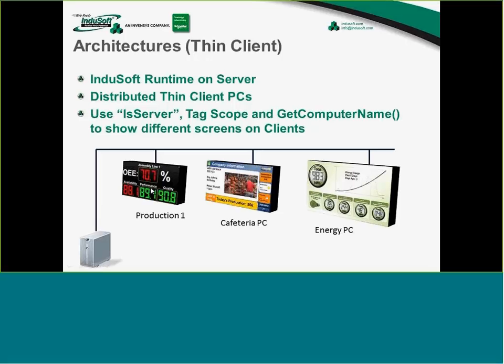Now, the really nice thing about the Secure Viewer client is that it can run an edge-to-edge full-screen application. You don't even know that it's not the full runtime, even though that runtime is remote. In fact, during the training class, sometimes I show, and if you haven't seen the online training videos that we have, one of the techniques that we talk about during the Secure Viewer application is creating a tag called isServer and setting that tag scope to local scope and determining, am I the runtime server, or if not, then I must be a client.